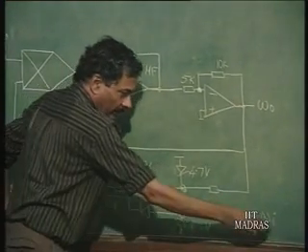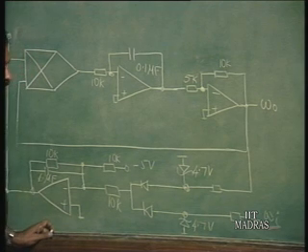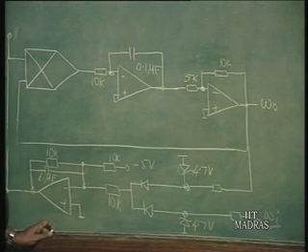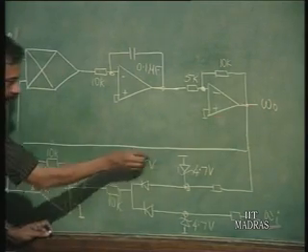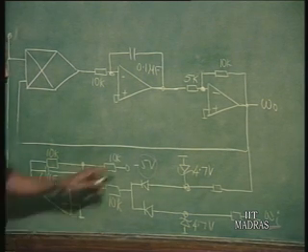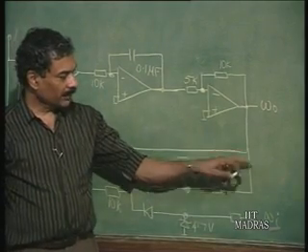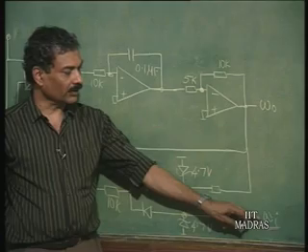So, we will now show you that omega I, if it is around, let us say 600 hertz or so, which is the free running frequency of this, which can obviously be adjusted by varying this quiescent voltage here. This is called tuning of the phase lock loop. It can be made to get locked to the incoming frequency, which is around 600 hertz or so.